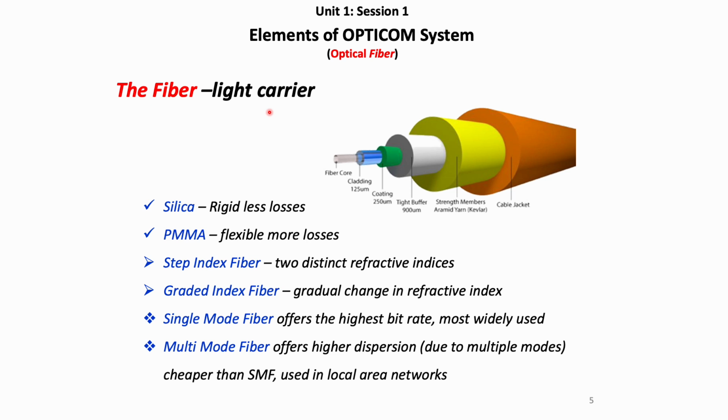Okay, once we have completed the transmitter and the receiver: the transmitter receives the electrical signal from the message source and converts it into the optical signal. The receiver receives the optical signal and converts it into the electrical format. The amplifier increases the signal strength. Amplifiers and receivers do the same.